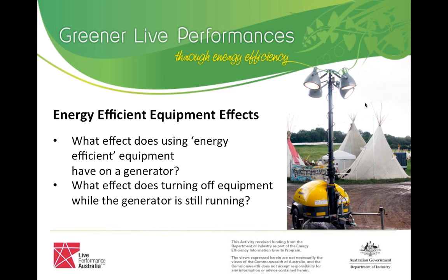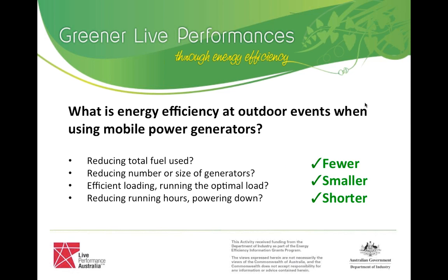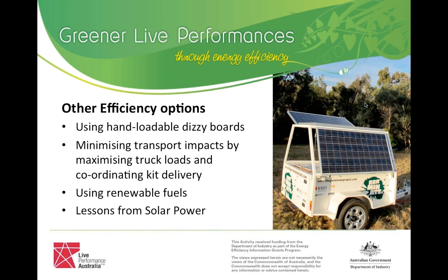Yes, I've been running some solar trailers that are essentially mobile solar-powered generators at events, running different equipment for a number of years now. I guess the key messages would be to reiterate some of the things that people have been speaking about regarding the petrol generators, but just to emphasise that matching the load to the generator is a little bit more complex. It's not a matter of just flipping a switch, you've got to match the sizing of the inverter so that you can bring it back to 240,